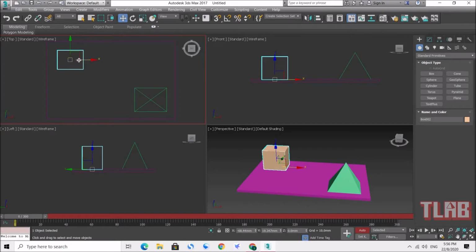Let's say I want to move the box until here, and I want to use 2 seconds. 2 seconds means 60 frames, so you need to move to frame 60. Or if you don't want to drag, you can key in here, put 60 and then enter. Then you can see it goes to frame 60 already. Now after you move the frame, you move the object again.